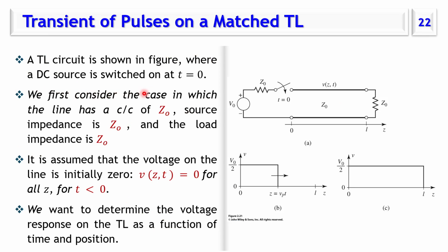So at time equals 0, we switched this on. Remember, this part is a lumped element part, so it doesn't have a physical dimension or length, but we're just drawing it like this to show that we have a source, and this source does have an internal impedance. So when we switch on, the load seen by the source is just Z naught.